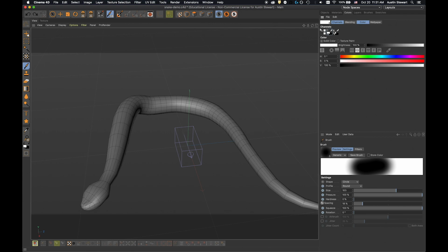Usually you don't want to do that, so I'm just going to deselect the brushes there and then select back here. Now, at this point, you'll see it says no, because I've deselected both of those little brush icons. This is one of the things that Bodypaint does that's kind of aggravating to me. It's really hard to figure out what you need to do to draw on something. Right now I've made it so I can't draw, and I'm wondering what the heck's going on. It's because I don't have this little pen icon or paintbrush icon clicked on here. Now that it's clicked on, I have the channel selected and I can adjust it.